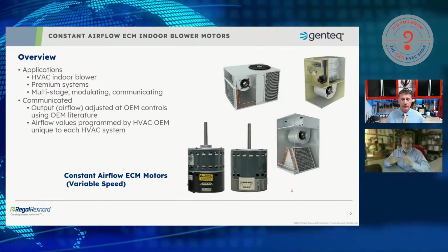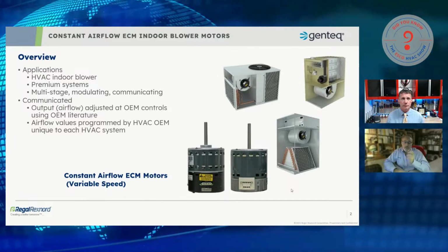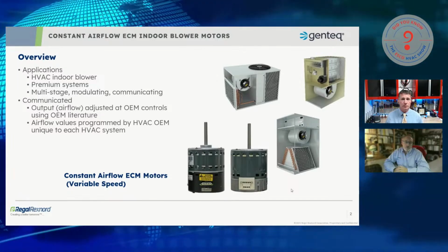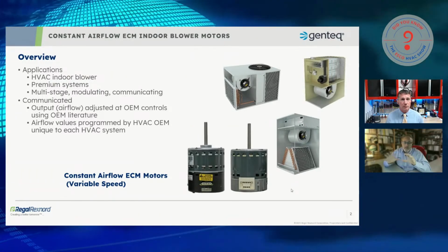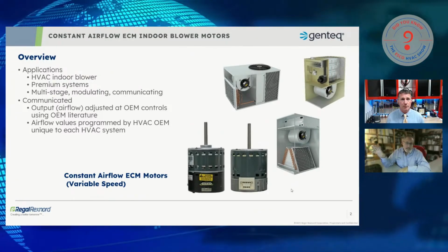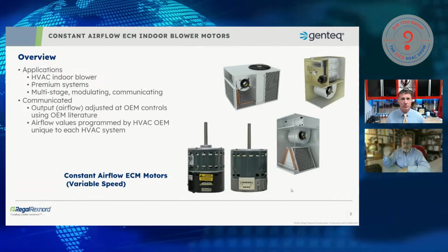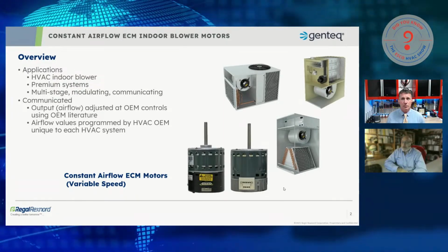To change the performance of the motor, you're going to be adjusting dip switches or jumper pins, or lately many manufacturers are moving to the fully communicated system, where the thermostat's communicated and all the menu selections and even fault codes are at the thermostat.